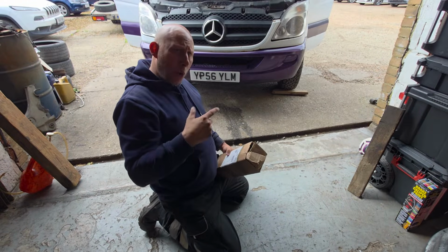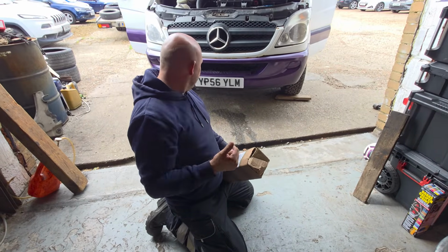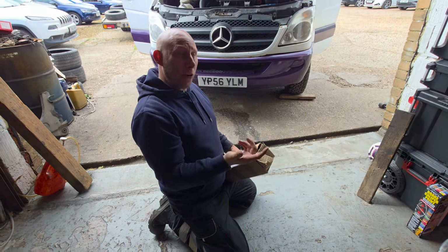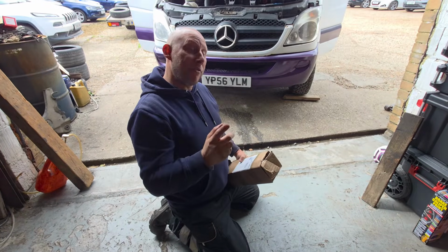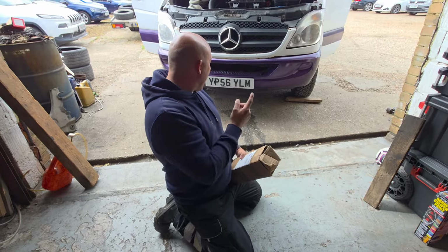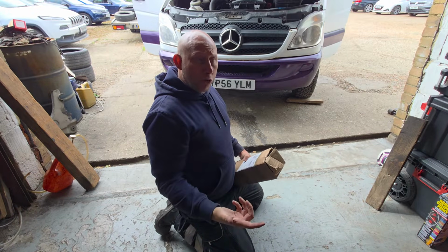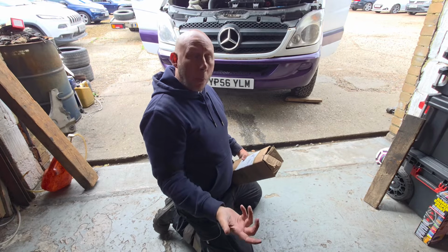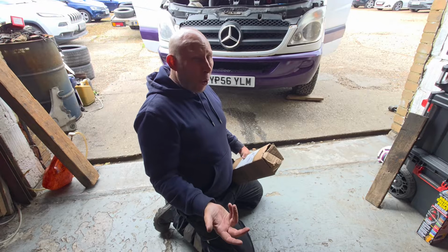Right, people, we are back on with the Mercedes Sprinter. Now, those who watched the earlier part of this video, because I'm hoping to do it in one, will know that we had in the live data a negative pressure in the exhaust system. Now, we went underneath and we found that the flexi joint had come completely apart on the exhaust system. So we was getting a boost reading that was different. We had a problem with the differential pressure. We're showing a negative, which we know a negative pressure in there normally is a crack.